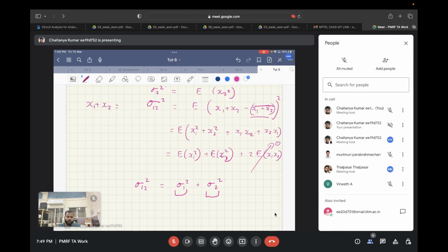So you don't see too much non-linearity because that node is not swinging. Mainly the processing happens through linear elements, the resistor or the capacitor. V equals IR holds in a resistor. So that's why the active RC network is more linear, but the GMC network is less linear.